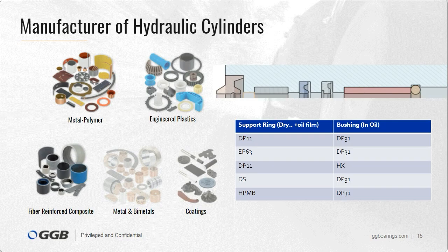But the fiber reinforced composites and engineered plastics are really the best way to approach corrosion, just remove all doubt, right? Those are not going to rust. They're not going to create couples or anything like that. Some added benefits there: we also get electrical resistivity. We can have magnetic permeability as a requirement in some applications. So, like I had mentioned, there's not really just the one thing that points us to one material group or another. It really is a wide range of decision making and inputs to select the right material.